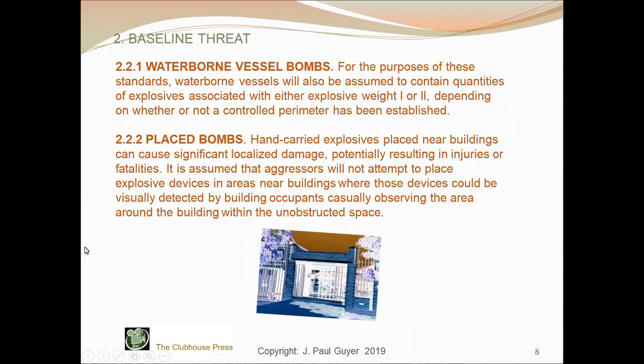So the explosive weight is the basis for the standoff distances associated with a controlled perimeter or situations in which there is no controlled perimeter. Standoff distance, the perimeter, in other words, you are implementing measures to see that people do not approach a building without going through a checkpoint.